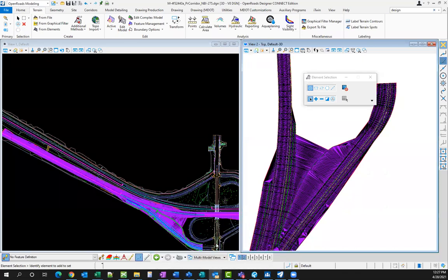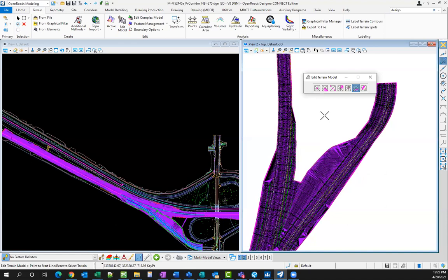So Luke, for this boundary, then when you display the triangles, first you got to unlock it, right? So you can clean up the triangles. Yeah, yep. So to clean them up, you would deactivate the rules, and then you have these edit model tools. I usually like to use this one. I'll just pick the terrain model, delete a bunch of triangles.